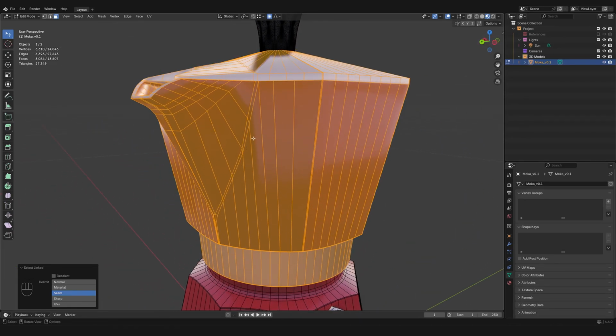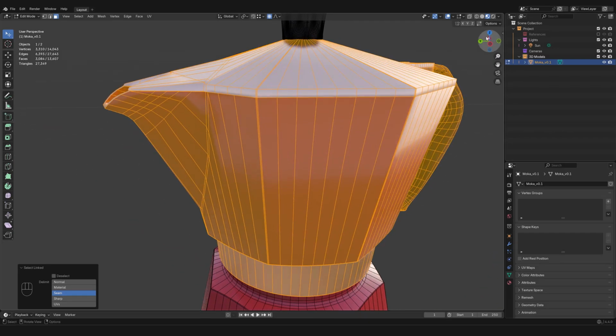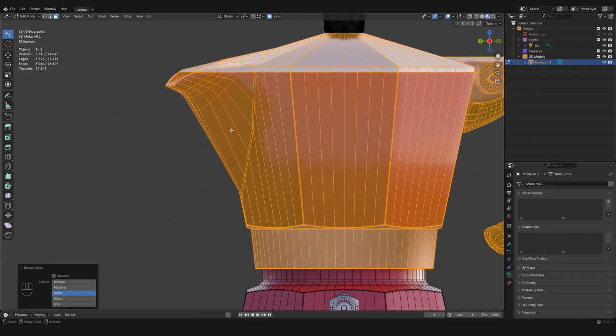And then let's suppose that I wanted to fix this part. What I would probably do is deselect those parts that got selected right now that I didn't want to have selected. And so right now I have activated the X-rays, and then I'm going to use C to bring up my brush selection.